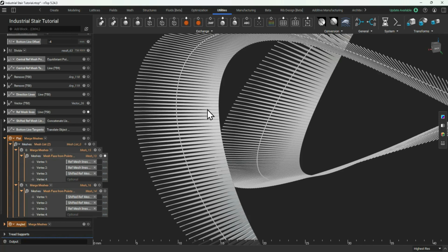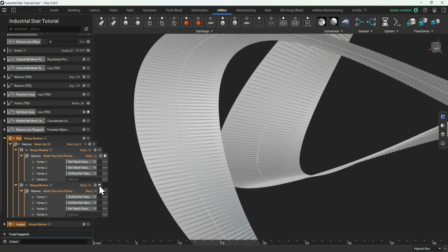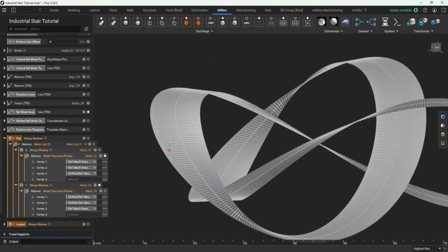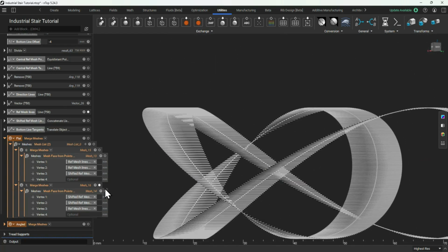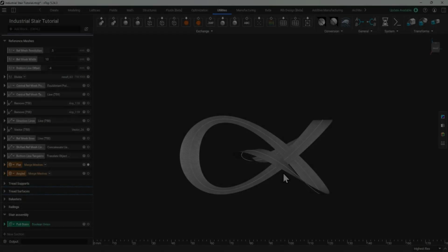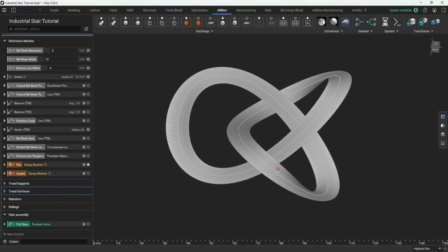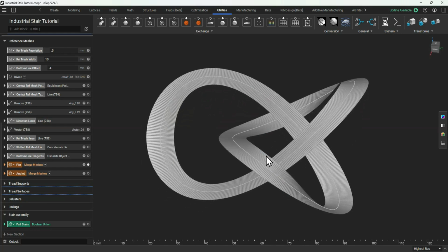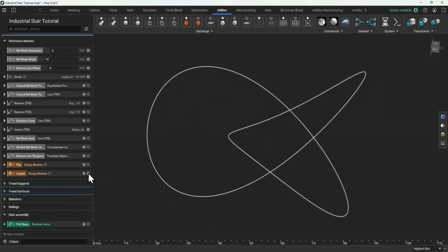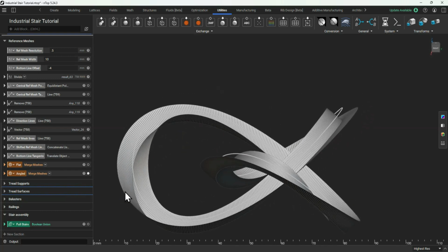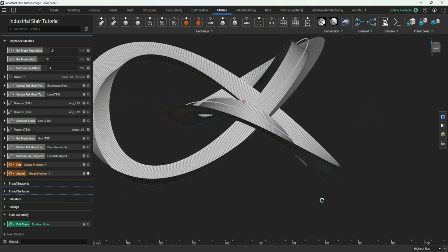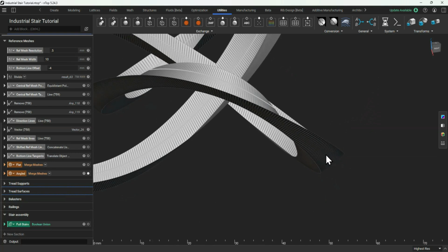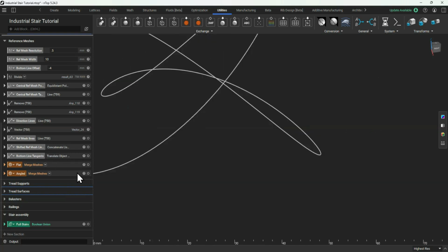Now you can't use 4 points as we did in the stairs because these 4 points are non-planar, so you have to create the surface using triangles. So there's one set of triangular meshes, and then the second set of triangular meshes just fills that in, and then you can merge it all together. We don't actually use this reference mesh in the creation of this particular procedural stairs, but what we do use is a similar reference mesh that creates a triangular base at the bottom, an angled point at the bottom.